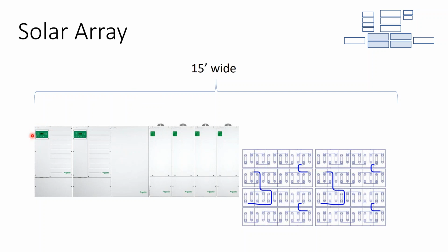You have to take that out and put in the functional screen that you actually need. It's a requirement to commission this system. And I'm just thinking, well, why don't they just put that screen on to begin with? Well, it's because you might be double or triple or quadruple stacking the inverters, and you only need that screen on one inverter and not four.